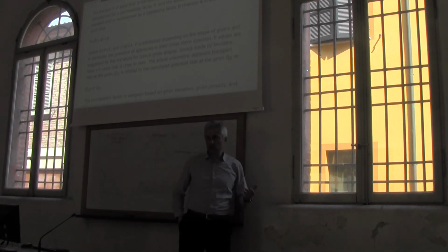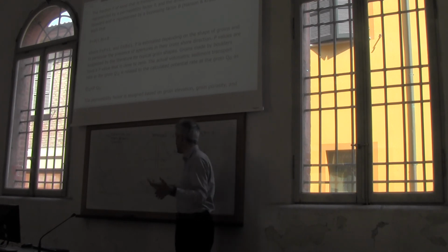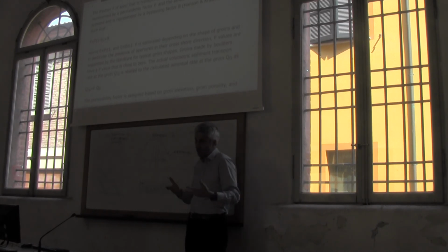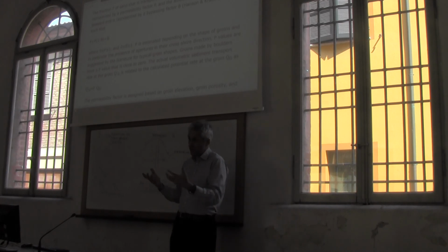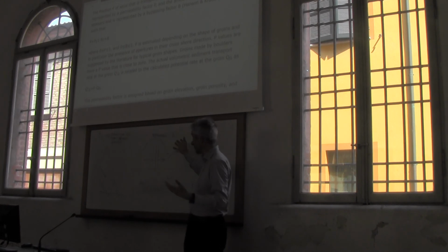You may say there is a lot of uncertainty in there, and particularly in the estimation of bypassing. Of course, while in the estimation of permeability, we have some guidance. In the estimation of bypassing, everything depends really on a series of processes which are the characteristic wave behaviors, the long shore sediment transport as a whole, the shape of the beach. So this is more difficult to understand.